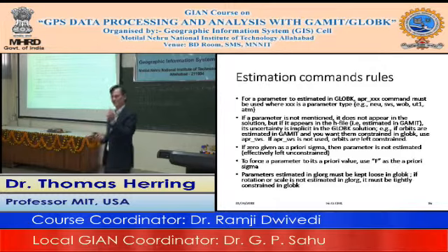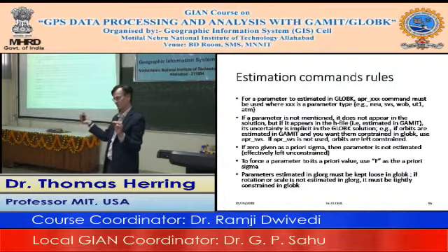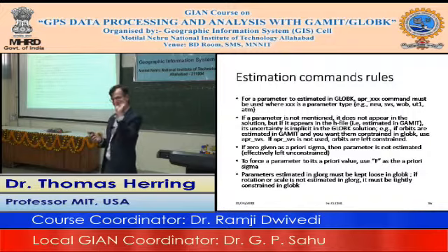Now the atmosphere is passed through from GAMIT. This only works with the GAMIT H files. It's passed through as a single mean value for a station. It's not the time variation that you estimated in GAMIT. It's actually the mean. And when you look at the output atmosphere estimates in GAMIT, you'll see there's a mean, and then the differences are from the mean as a function of time. The idea of this command is when you do network merging together, the common sites between the networks, this APR atmosphere command will make the atmospheric delays the same at all of the common sites.